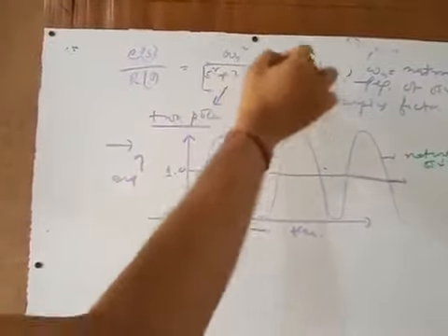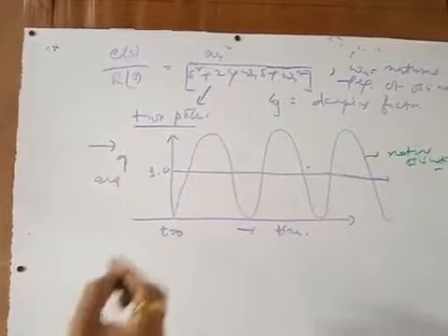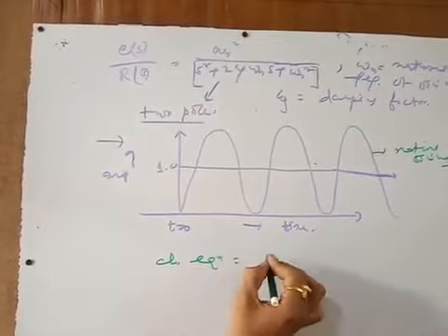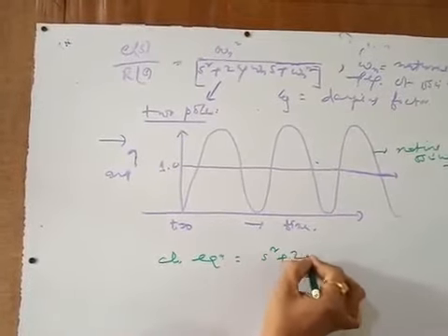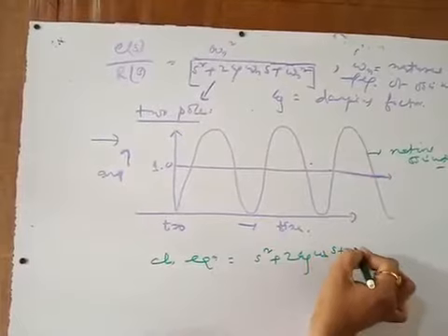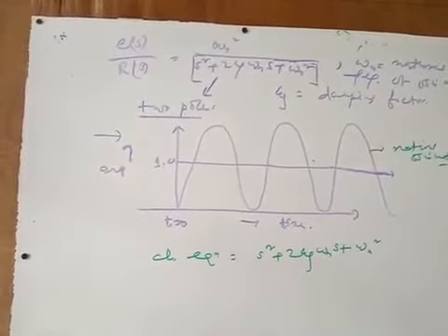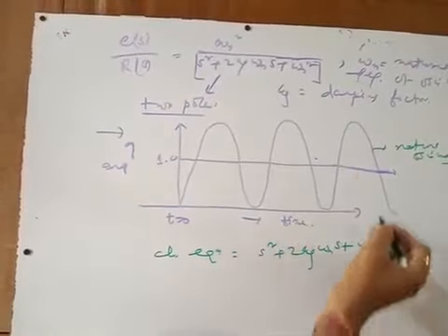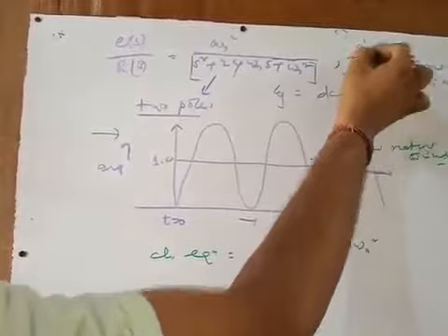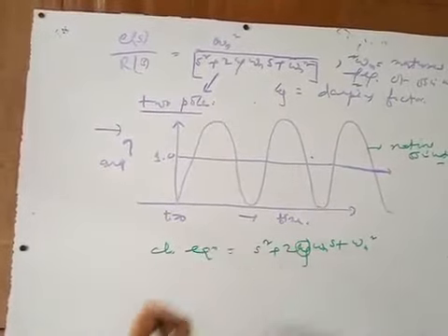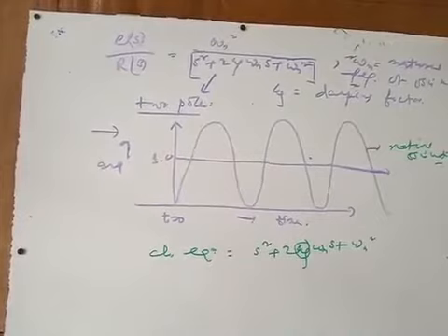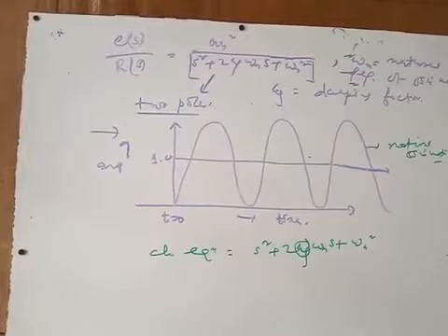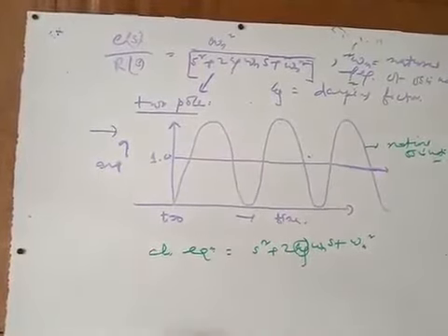When there is natural oscillation, you see from this mathematical formulation what happens. Just note down the denominator part, the characteristic equation, that is s square plus 2 xi omega n s plus omega n square, and the terminology is such that the natural frequency of oscillation is omega n. Now when this damping ratio or damping factor is applied, that means when you are applying certain kind of damping, you can read in some measurement chapter that damping is essentially to reduce the oscillations.